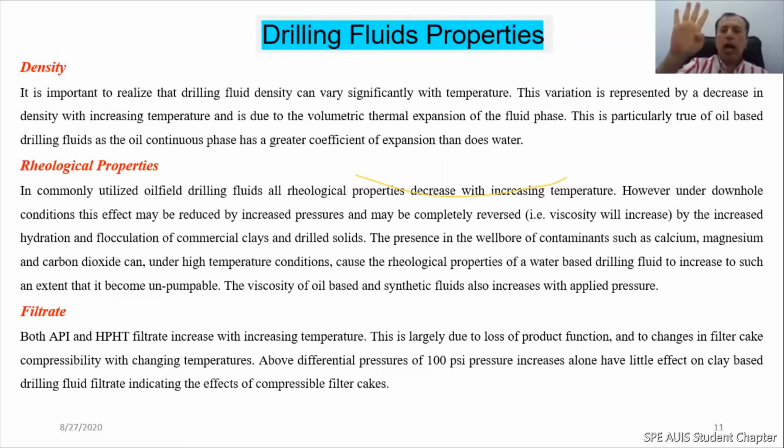You will decide whether that drilling fluid or drilling mud is suitable for the drilling operation at that depth or not, at that temperature or not, at that specific type of rock or not. So you will decide based on what? Those four parameters: depth, temperature, pressure, and type of formation.